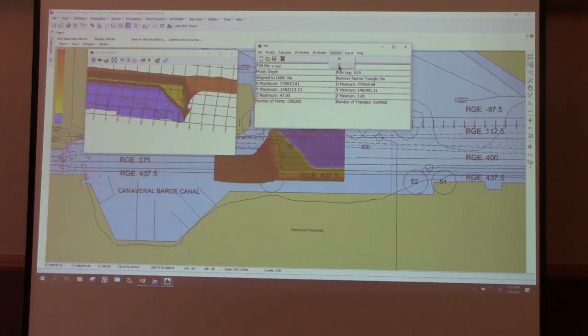I hate the cross sections in tin model. Hate. Can we switch from single beam to multi beam, so from average end area to tin, and to produce the deliverables that our customers are used to, trying to use tin to create cross sections, it's so ugly. I usually export a log file, open it in cross sections and volumes just to produce some pretty cross sections for the customer. But I guess I can trash all that maybe and try to sell them a 3D tin, with plan lines overlaid on top. It shows way more than a cross section anyway.